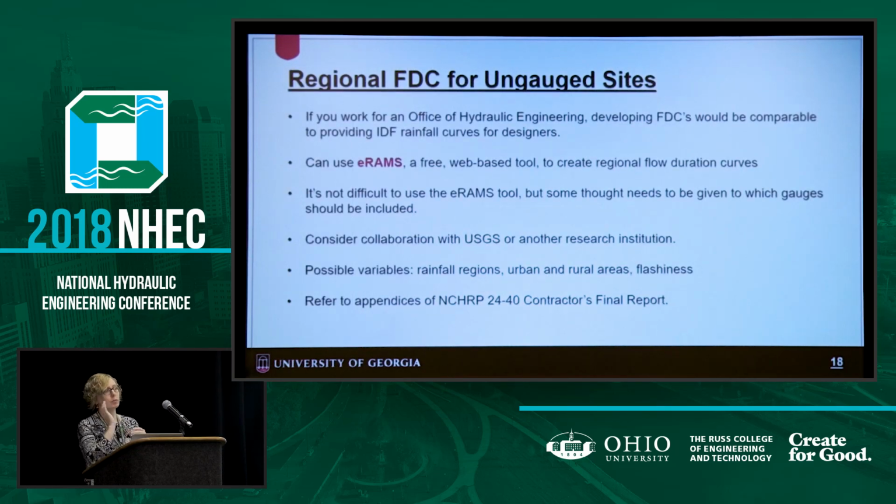Okay, so if you only remember one thing about flow duration curves, I want you to remember that you can have a regional flow duration curve for ungauged sites. If you work for an Office of Hydraulic Engineering, I would say that developing these flow duration curves will be comparable to providing your IDF rainfall curves for designers. I would not expect your typical roadway designer to come up with these.